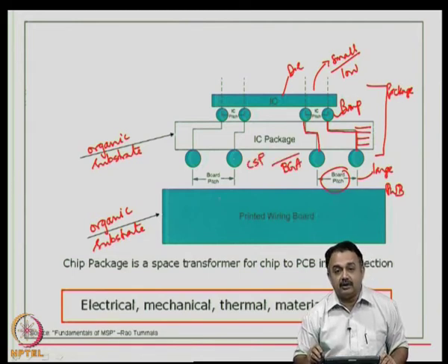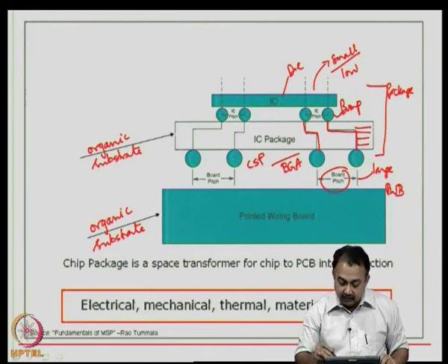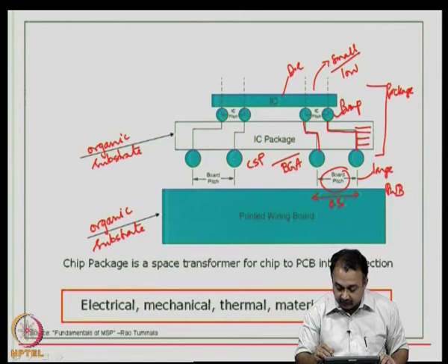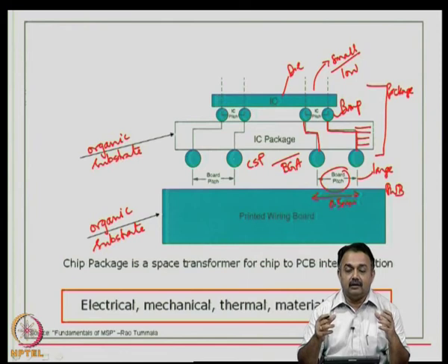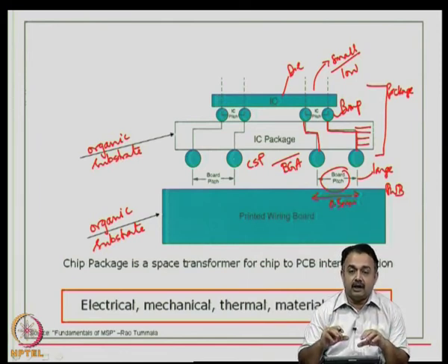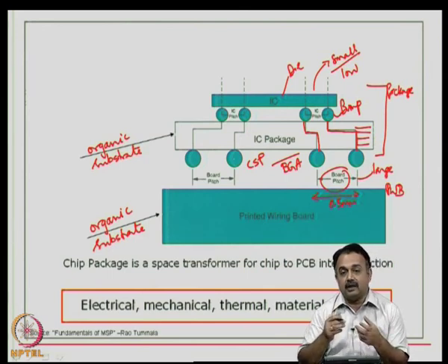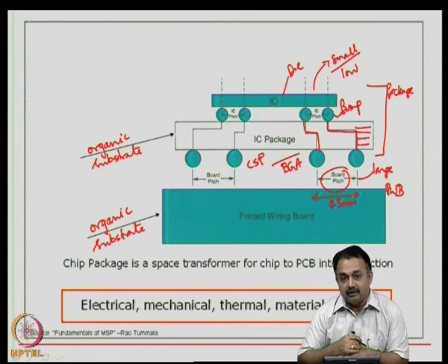These are advanced packages, and you are able to handle this kind of a pitch. Let us say this is 0.5 mm or 0.3 mm. You are now able to handle this size of pitch when you look at technologies available to mount this particular device onto the printed wiring board and establish a second level interconnect.